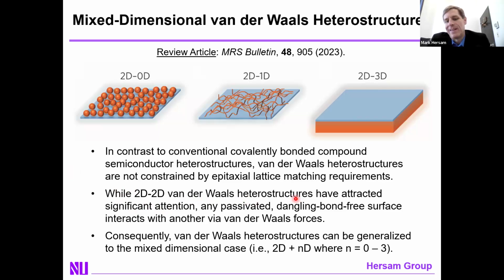But what we contend is that any passivated dangling bond-free surface interacts with another via van der Waals forces, and as a result, you can generalize this beyond 2D materials to the mixed dimensional case, where, for example, you could have 1D carbon nanotubes directly interface with 2D molybdenum disulfide.